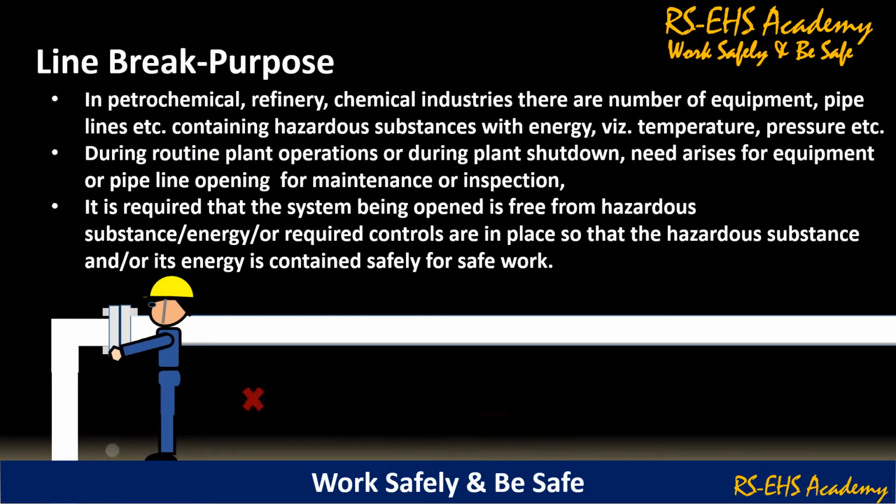Line break purpose. In petrochemical, refinery and chemical industries, there are a number of equipment and pipelines containing hazardous substances with energy, that is temperature, pressure, etc. During routine plant operations or during plant shutdown, the need arises for equipment or pipeline opening for maintenance or inspection. It is required that the system being opened is free from hazardous substance and energy, or required controls are in place so that the hazardous substance and or its energy is contained safely for safe work.